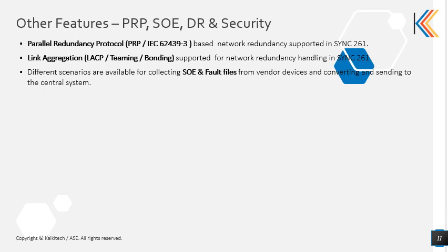Using the vendor interface, we can collect the disturbance and sequence of event files from the vendor IEDs and send them through the Ethernet using secure FTP or other protocols to send these files out to the upstream.